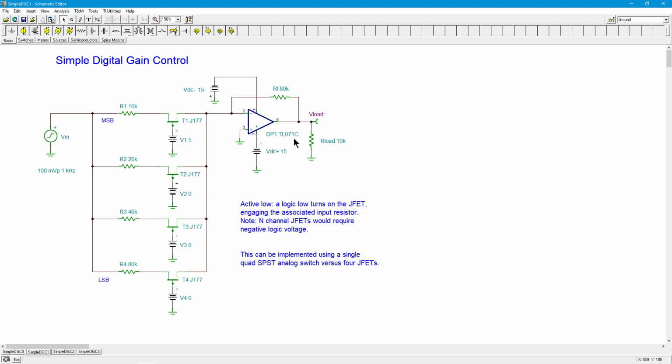Now, the TL071 is a FET input op amp, so the currents aren't so bad, but the VOS, the DC offset there on the input end, VIO, is kind of high, maybe 3 millivolts, something like that. If you had a newer FET front end op amp like an LF411, the newer generation, that would be down by an order of magnitude or more. So what we just saw for the offsets would not be as bad.